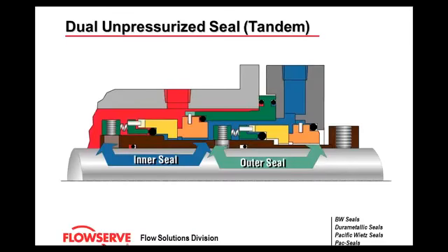Now here's a dual unpressurized seal. Now I left the term tandem in there. Some of the old nomenclature from years back was to call tandem seals unpressurized and double seals pressurized. Today, the terminology is dual unpressurized or dual pressurized.